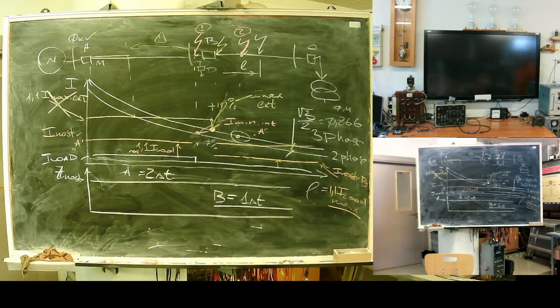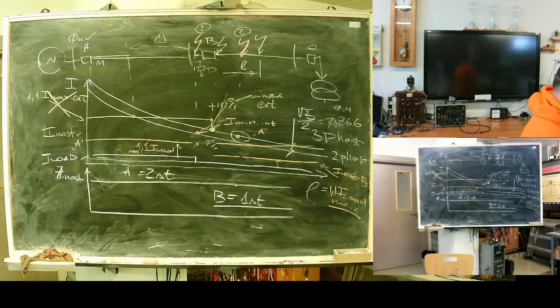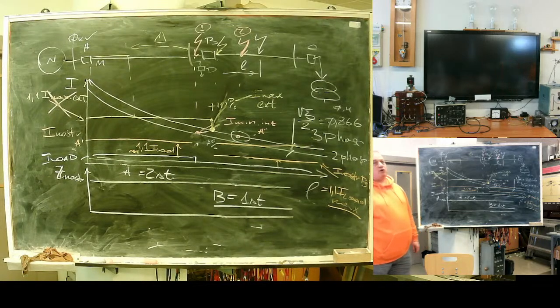Guaranteed. Second, you need to give some time for the circuit breaker mechanics and some spacing for your time function error. So on average, for distribution networks, the average is half a second.